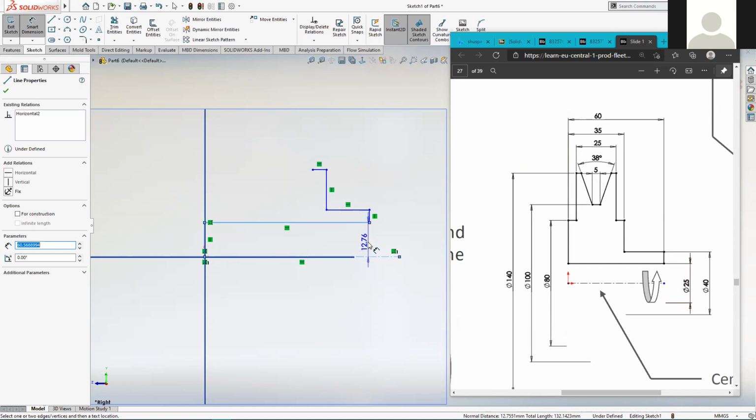So yeah, we did this the other week, but even in the other session earlier this week, I was asked by people, could I not just dimension everything as a radius? And I've just given them the answer that I've given you. You could, but you'll be out of step with the rest of the engineering world. They tend to use diameters when it's rotational parts such as this. So it's good to get this skill practiced and get it in your head.